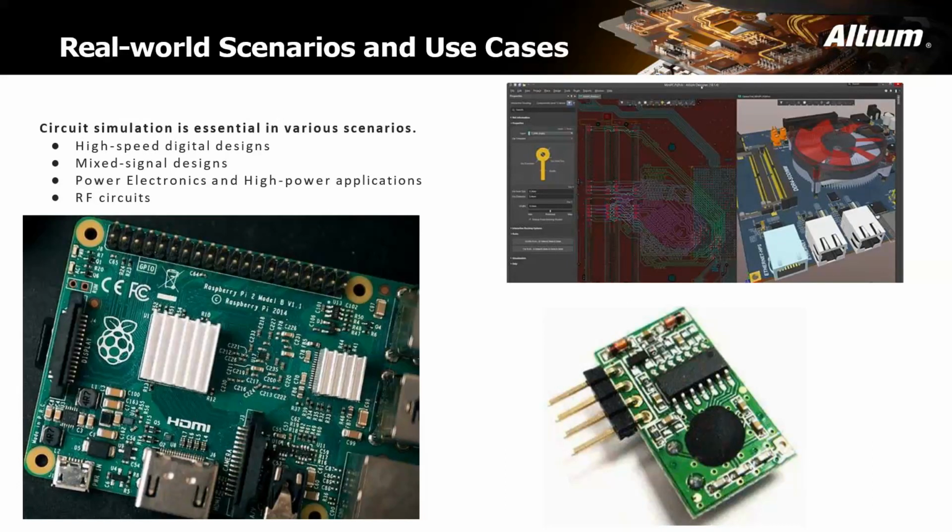Next, mixed-signal designs, which involve analog and digital components, often present unique challenges. Simulation plays a vital role in understanding the complex interactions between the components and verifying the entire system functions as intended. For example, designers can perform sensitivity analysis to determine the impact of component tolerance on the ADC's performance. It helps to optimize the design and ensure accurate signal conversions.